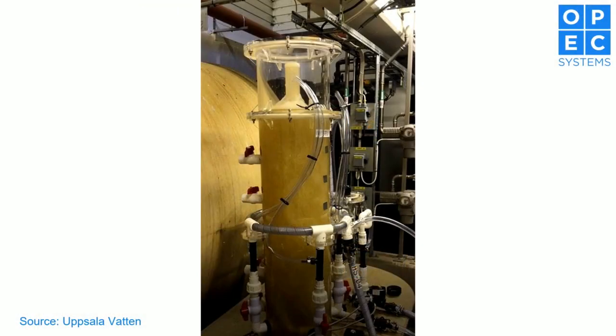And so what we're able to do with those plants is run a sort of treatability study, if you like, on a client's water source. First of all, using our predictability model, we can do a bench top exercise to say, look, we think you're probably going to achieve this level of result based on your particular PFAS signature. So bearing in mind excellent performance for long chains, declining performance for the short chains, based on your mix, we'll be able to tell you just how much work you're going to do.